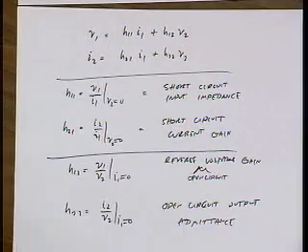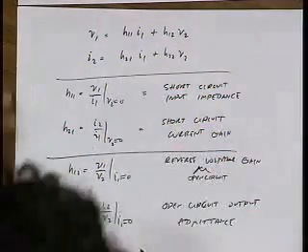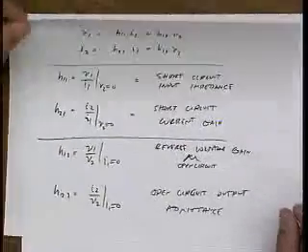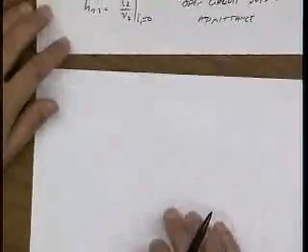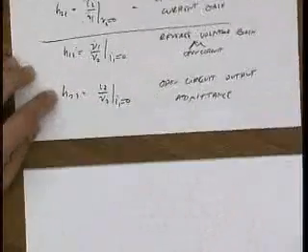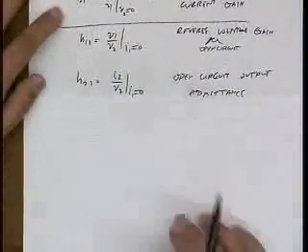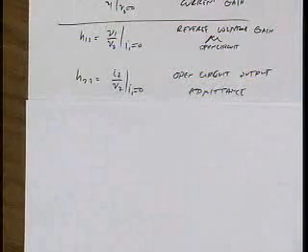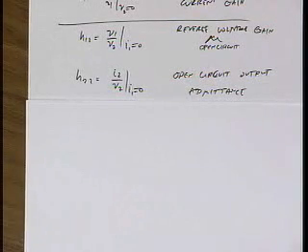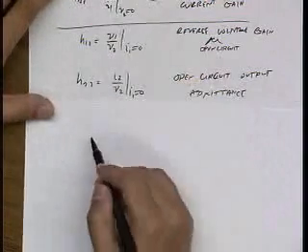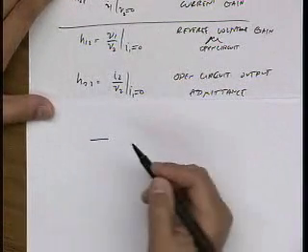And whenever I don't like working with numbers, just 4 parameters, they don't make sense to me. I like to see pictures. Maybe you're a numbers person, maybe you're a pictures person. I'm a pictures person, so when I see these 4 parameters, the first thing I'm hungry for is an equivalent circuit. And so it's very simple. The equivalent circuit should look something like this.